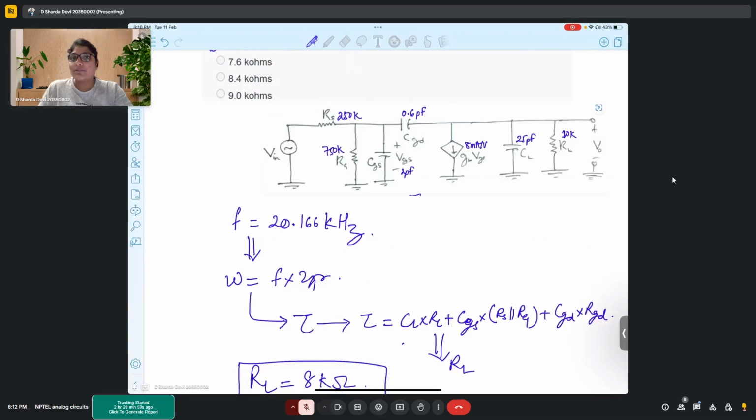But I have a doubt about why the pole frequency was increasing. The graph of the low frequency response was in increasing order, not decreasing order. If it is increasing in order, that means there are more zeros in the system compared to poles. That is the inference you can get. But unless you solve the transfer function, you will not understand where the zeros are coming from and what their values are. For that, the transfer function needs to be solved.